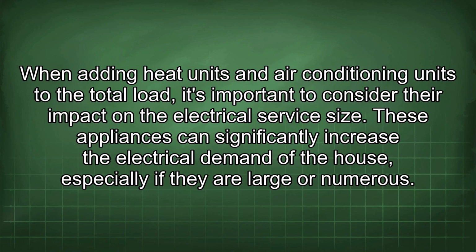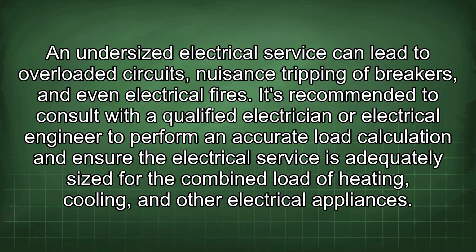When adding heat units and air conditioning units to the total load, it's important to consider their impact on the electrical service size. These appliances can significantly increase the electrical demand of the house, especially if they are large or numerous. An undersized electrical service can lead to overloaded circuits, nuisance tripping of breakers, and even electrical fires.